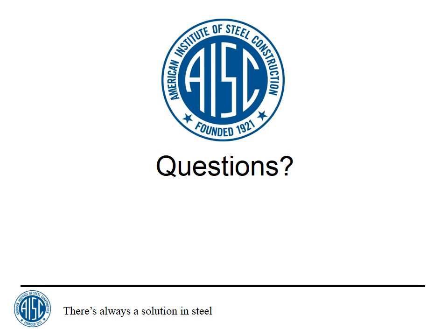Okay. Next question. How can prying action be addressed with double angles welded to the column? Like, say, welded to a column flange, maybe? I don't think that you should use that type of connection, because you've got welds way out at the toes of the angles. A very ineffective way to carry any kind of an axial force, an H sub C force or a transfer force.